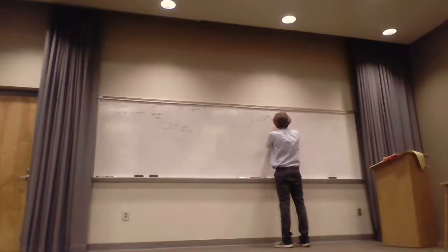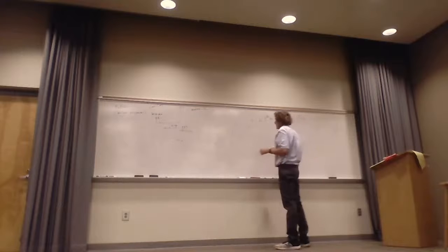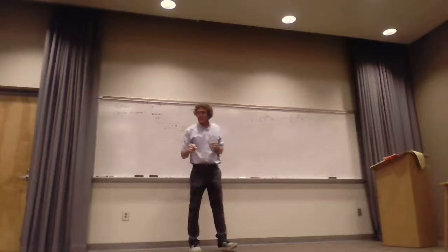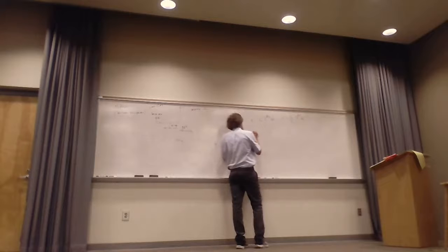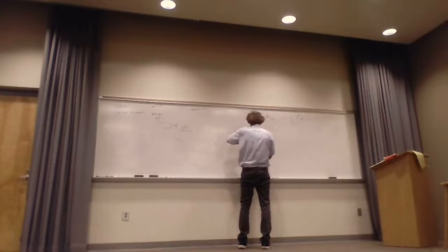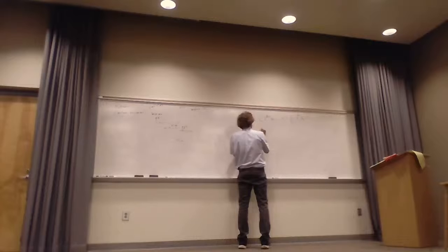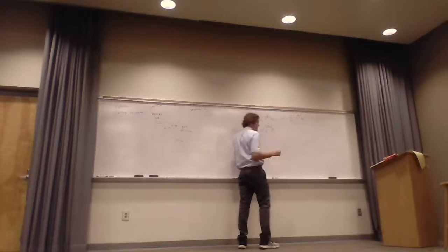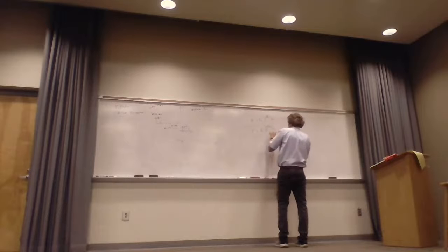So that means the H field, its incident would be that E field, E naught incident, over eta, whatever eta 1 is, the intrinsic impedance of region 1, e to the minus j beta 1 z in the AY direction. Now, eta could be complex, but I'm assuming it's lossless, so it isn't. That's the incident field. When I take a look at the reflected field, that's going to be equal to E naught reflected, e to the plus j beta 1 z AX. It's the same. I just copy that down, except the exponential here.